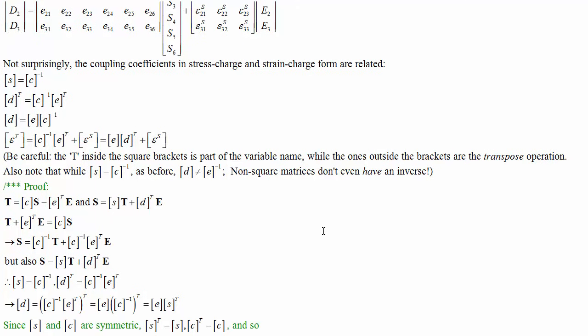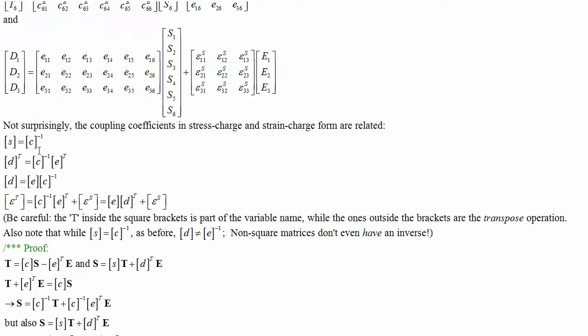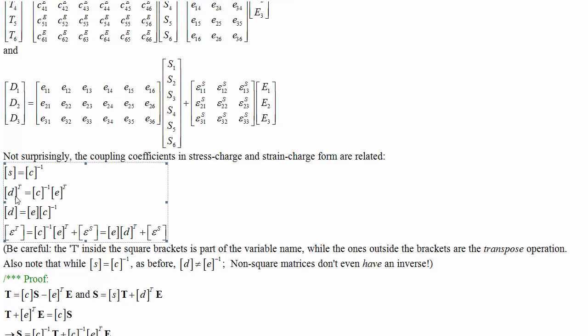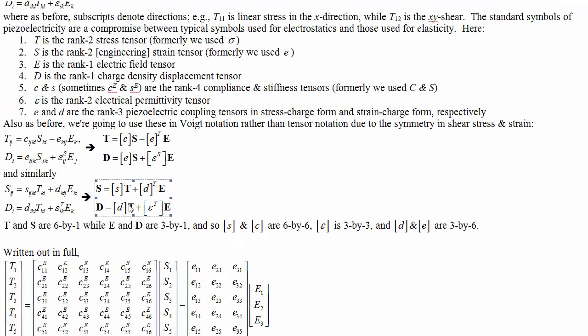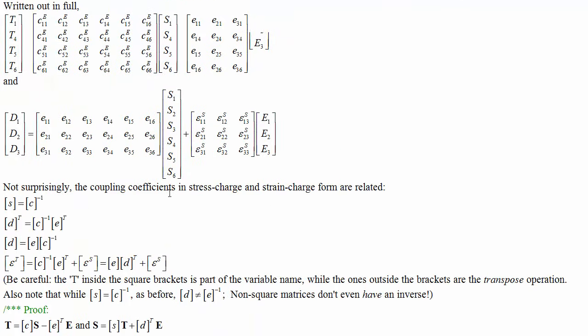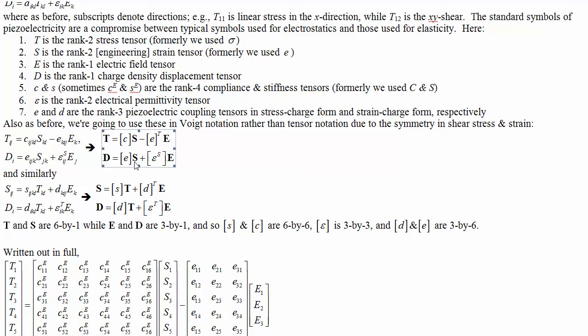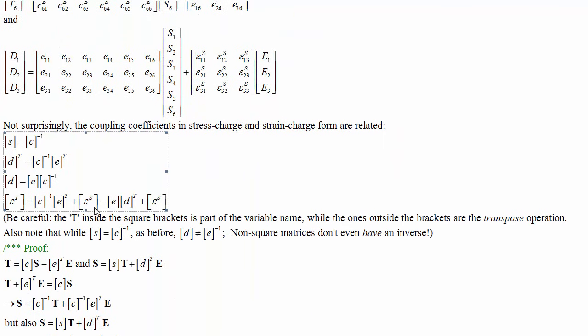All right. So the coupling coefficients are related as before. Conveniently, here's one situation where it works out in our favor. So we've got that the compliance is still the inverse of the stiffness. Yes, minor victories for mechanics, right? Okay, now the other ones, the piezoelectric coupling coefficients are related to each other through the inverse of the stiffness, which again is the compliance, and the epsilon T, which is the epsilon in the electronics equation that has a stress in it, is related to the epsilon S, the one in the equation with the capital S in it for strain, through this equation, through the coupling coefficients.